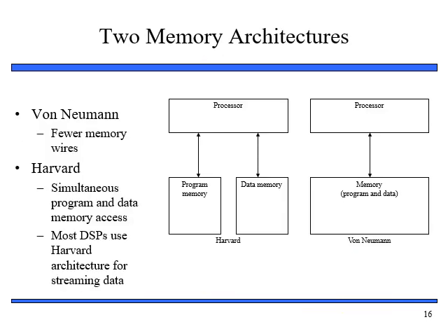In this slide we are going to discuss the two widely used memory architectures in general purpose processors. First of all, let's talk about memory. Memory serves the processor's medium and long-term storage requirement, whereas registers serve as short-term storage. We can classify stored information as program or data. A program is a sequence of instructions that cause the processor to carry out the desired functionality, whereas data represents the values of input and output that are being transferred to or from the program.